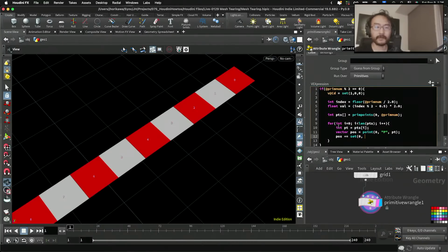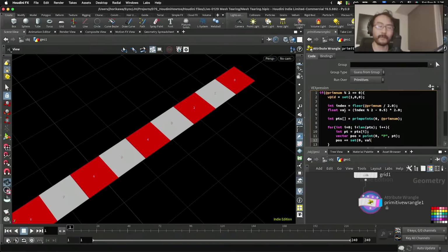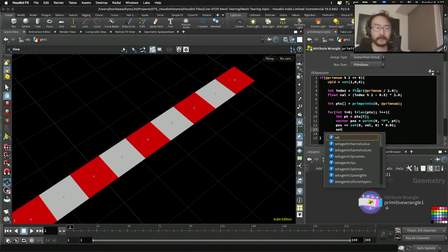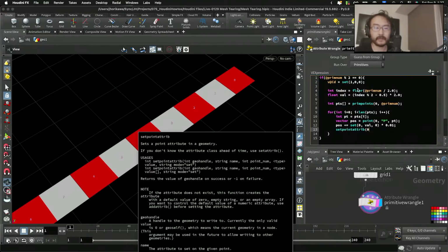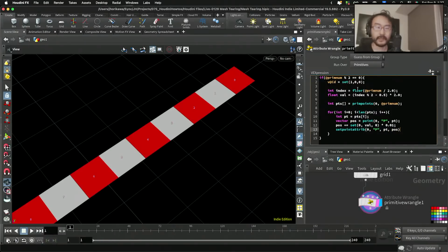Since I only want to move it in the y direction, you could just place the value that I've created here, which is going to be either +1 or -1, multiplied by how much you want to move. The value that you choose here doesn't really matter what it is, because it's just to make the geometry open. Having a big value is fine, having a small value is fine, unless it's big enough to make it look like it's opened up. So let's make it 0.01 and finally update the point position with the newly updated positions.